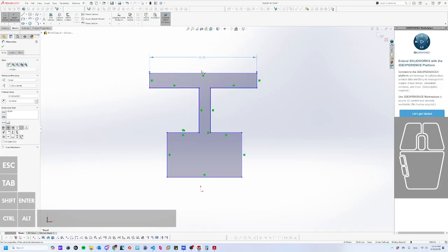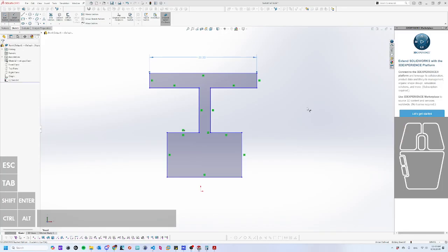Okay. The first dimension that you plop down on a drawing rescales the rest of the drawing so that it matches. Afterwards, any additional dimensions will manipulate the drawing to try and make everything work out. So before you plop the first dimension, that is when you want to fix your units. Otherwise, you might get into a sticky situation. So I mentioned in class that when I'm constraining a drawing, half the battle is the dimensions and half the battle is the relations.